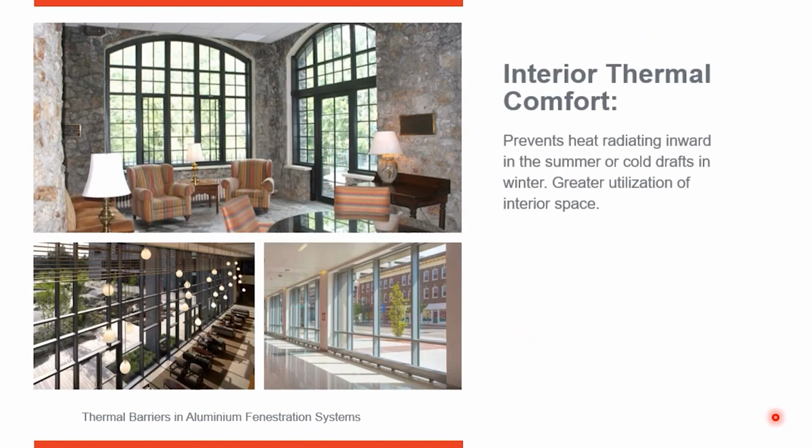If you look at this upper photograph, this is a facility in northern Midwest United States. So it's in a cold area. There's snow during the winter on the exterior of this facility. And if you notice, it's got a nice comfortable seating group right in the corner there with glazing on both sides of it. If this was a non-thermal frame, you would not be able to use that seating group during the winter. It would be too uncomfortable. You would have a cold area around that exterior glazing where heat was being pulled through, and cold on the inside would be considerably colder. So it wouldn't be comfortable sitting there.